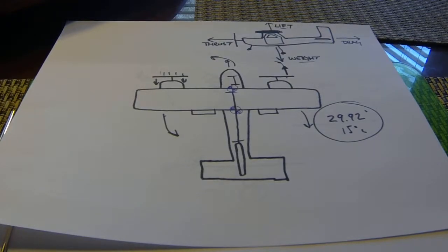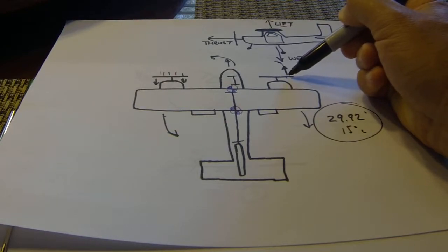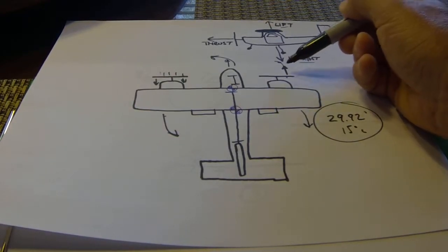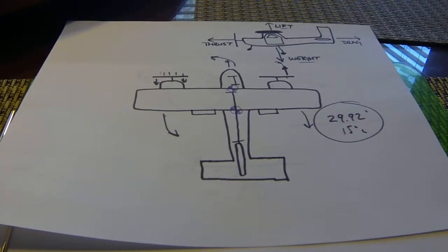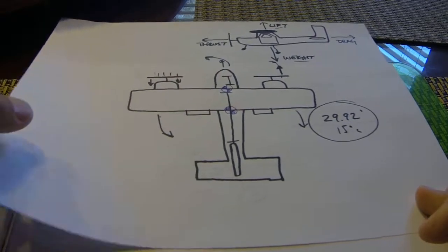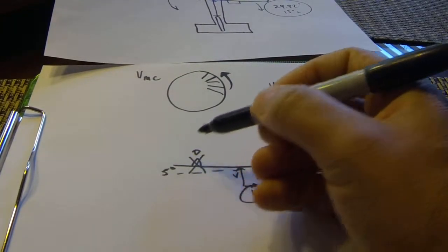Standard temperature and pressure, we talked about that. It's a baseline, right? Anything less, any higher density altitude, let's say, is going to lower our VMC. And I mentioned that earlier. It's going to take the performance away from the operating engine. It's going to create less of a thrust vector, which allows our rudder to keep up with directional control. Bank. All right, up to 5 degrees of bank. We talked about banking the aircraft, raising the dead engine, provides a horizontal component of lift on the rudder.